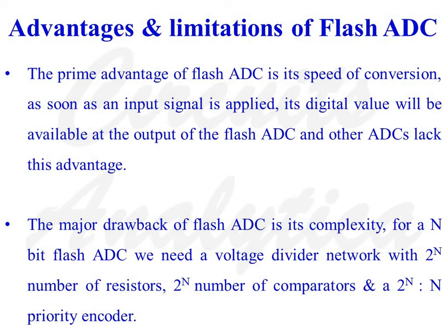Advantages and limitations of flash ADC. The prime advantage of flash ADC is its speed of conversion. As soon as an input signal is applied, its digital value will be available at the output of flash ADC, and other analog to digital converters lack this advantage.